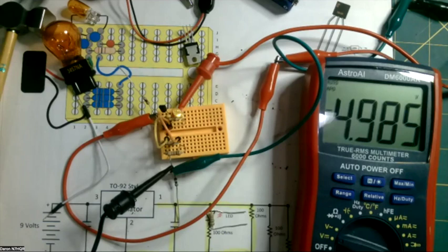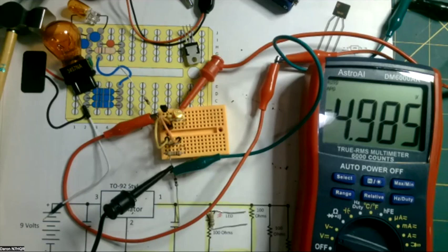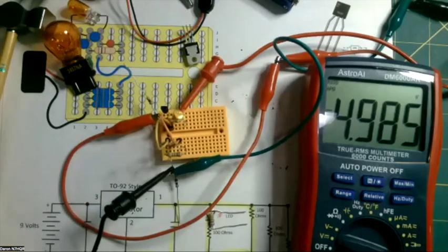Is there any way to reincarnate those critters or put them in the trash can? Actually, sometimes you can heat the cathode really hot by increasing the voltage to the filament to 10-20% over. I'm not sure exactly how much, I've forgotten. Then the filament gets real hot and it will actually bring more electrons to the surface.